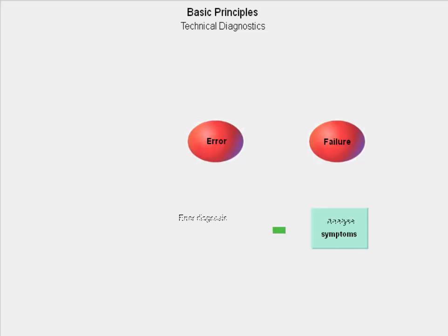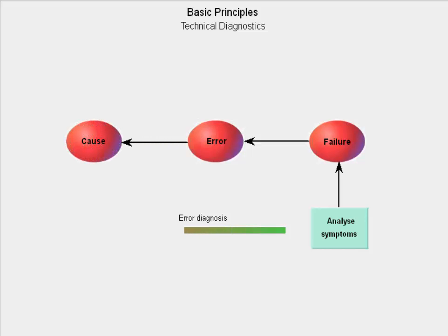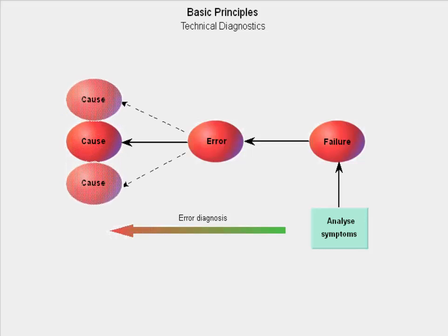In the course of the process, the significant symptoms captured by the monitoring system are analyzed and the cause responsible is determined. Considering that in practice there is a lot of ambiguity between the cause and effect, the diagnostics process can be a very complex one, which is why it is necessary to have extensive know-how and experience in processes and possible faults.